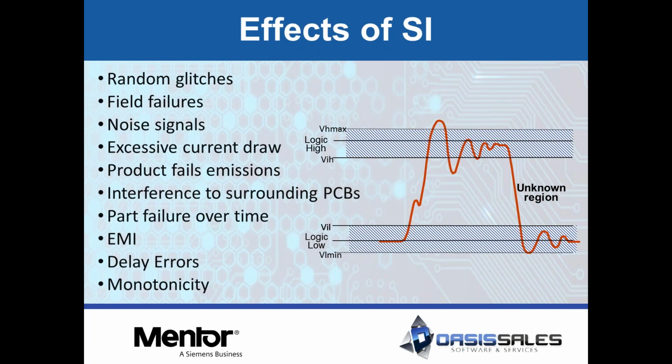If you look at a lot of the specs for components out there nowadays, they'll actually give you information in the data sheet that says, well, this part normally works at 3.3 volts, but it's tolerant to 5 volts. But if you keep hitting receivers with 5 volts, it can degrade the part over time. In fact, the part I'm going to be playing with today showed that any excessive hitting of the rail of 5 volts, the part may only last for about 10,000 hours.